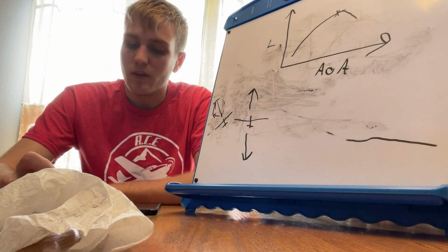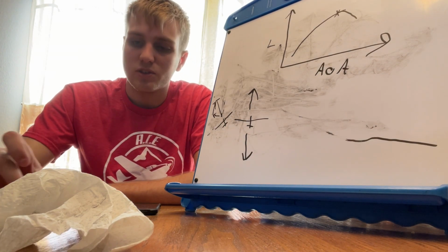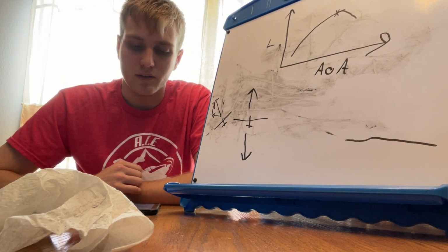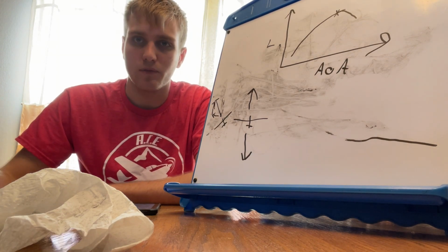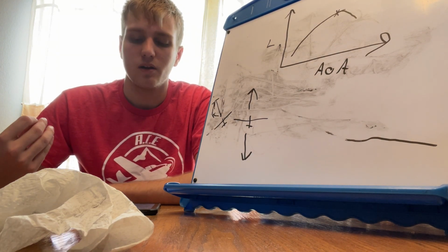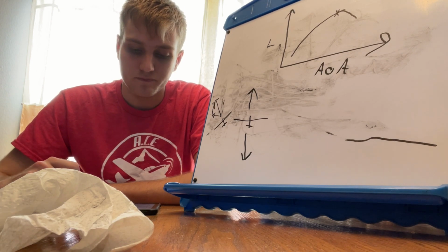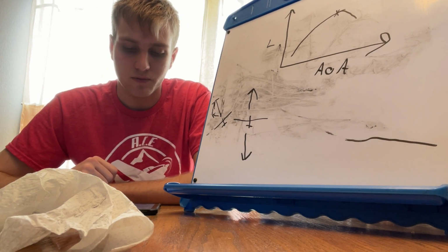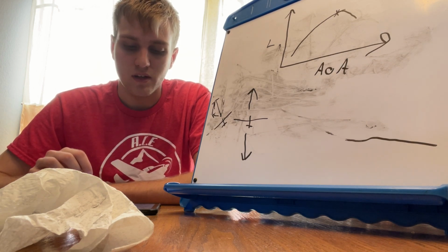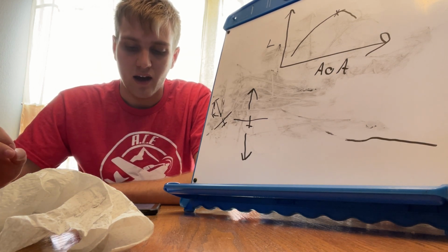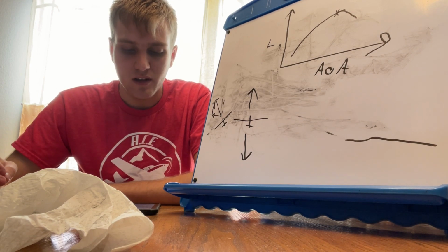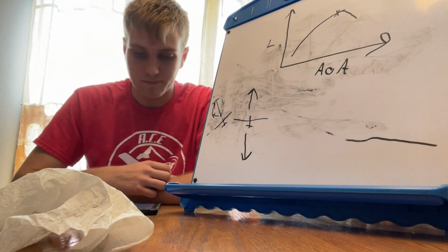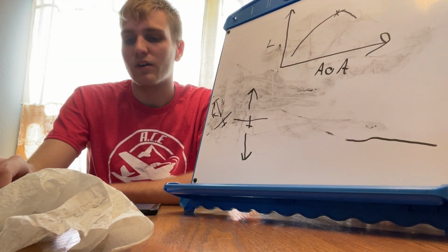And then finally, the most confusing one is gyroscopic precession. I'm going to read this from the book because it is very confusing, and I myself do not know the full reason of why it happens. Anytime a force is applied to deflect the propeller out of its plane of rotation, the resulting force is 90 degrees ahead of and in the direction of the rotation and in the direction of application. That was a lot. So let's think of our airplane here.